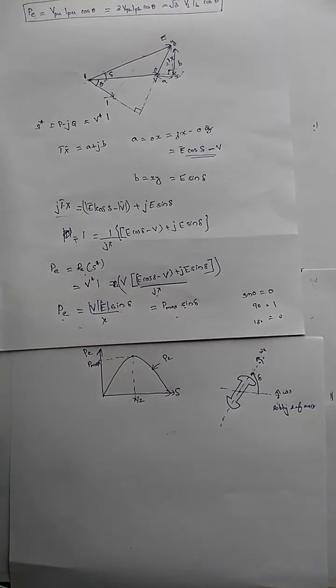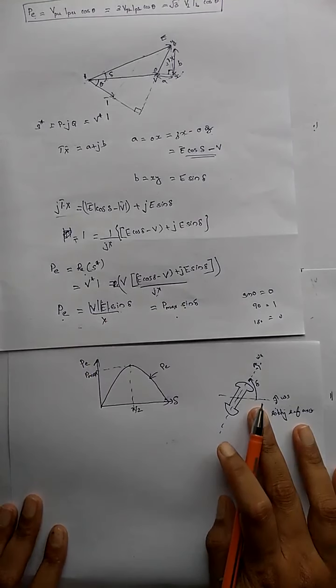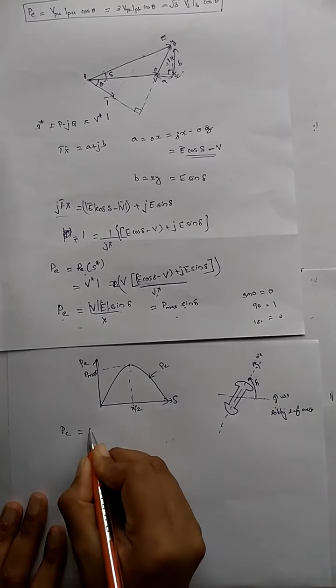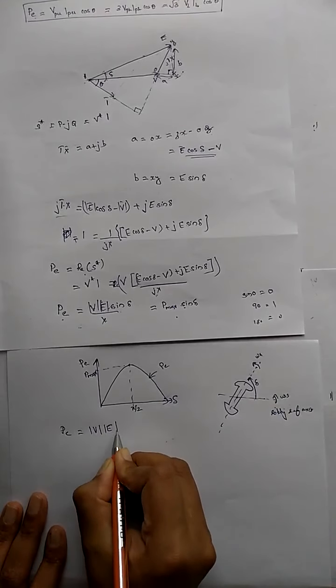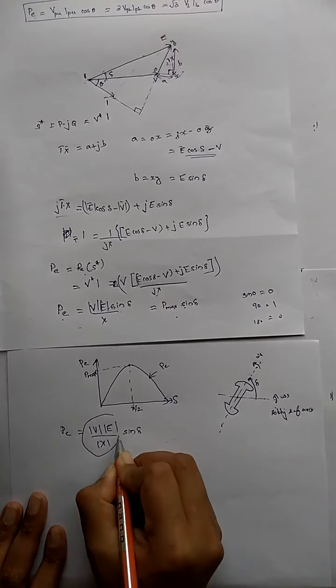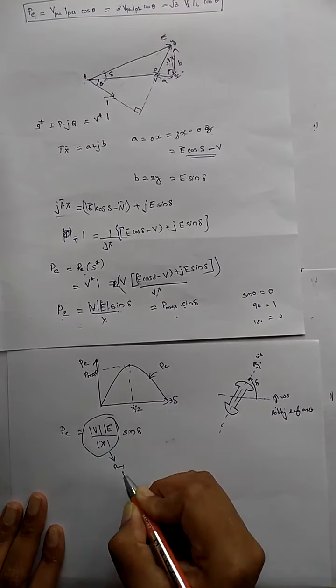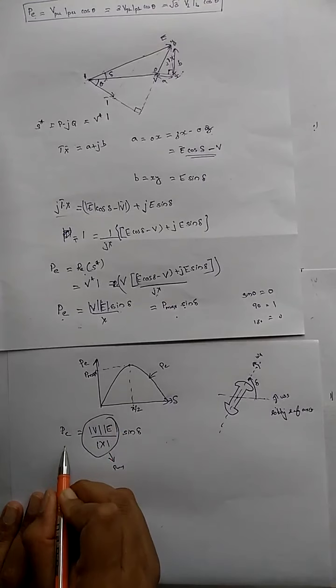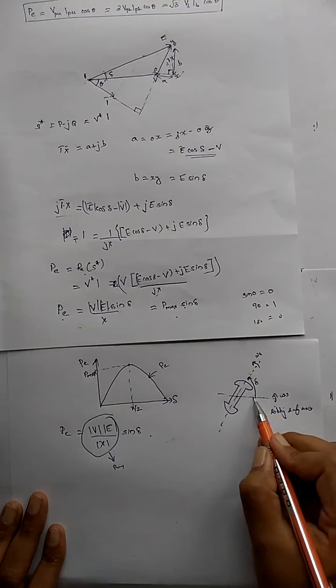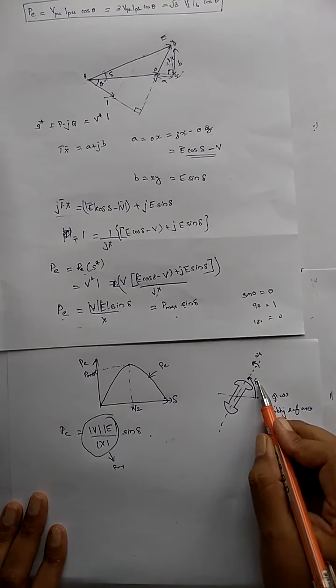If the load is constant and we are changing the excitation, I am writing the equation again: PE is equal to V into E by X, into sine delta. This entire term we call P max. If these are constant, the real power flow will depend upon the angle only, the load angle or rotor angle. So it depends on the rotor angle only.